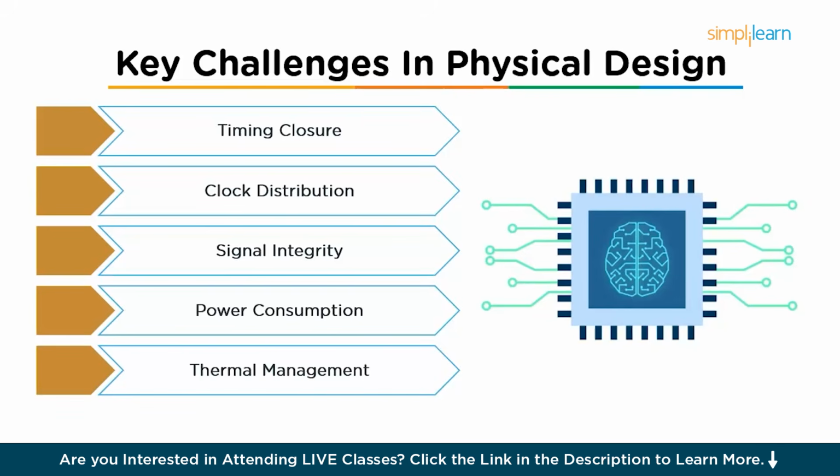Then comes thermal management. As power density increases, heat concentration can cause thermal hotspots that affect performance and long-term reliability. So the designer must plan for effective thermal distribution through floor planning, heat-aware placement, and spreading high-power components apart.